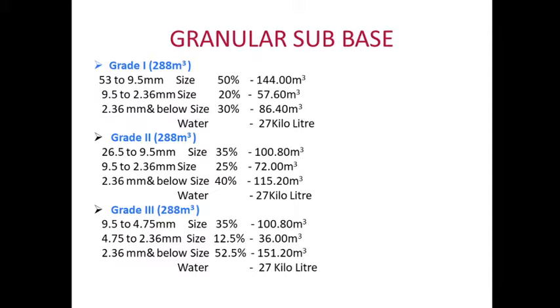Water required for preparing 288 cubic meter of granular subbase is 27 kiloliter. Everywhere in India, the subbase is granular subbase.